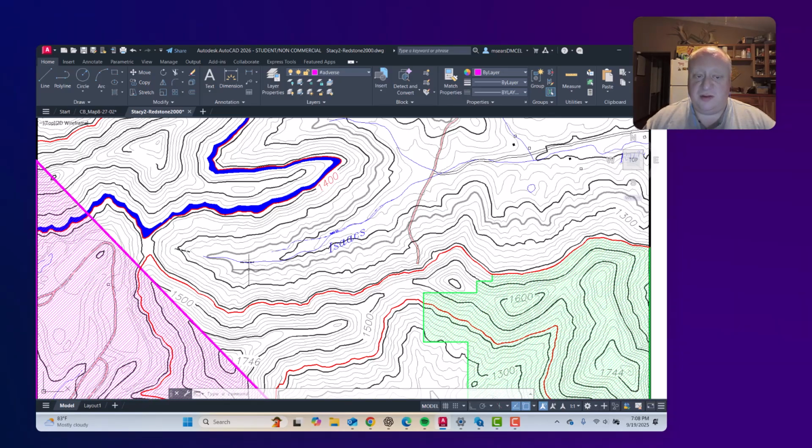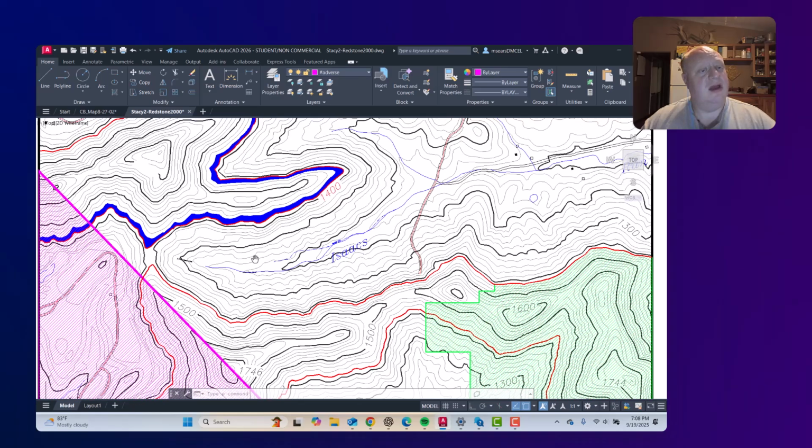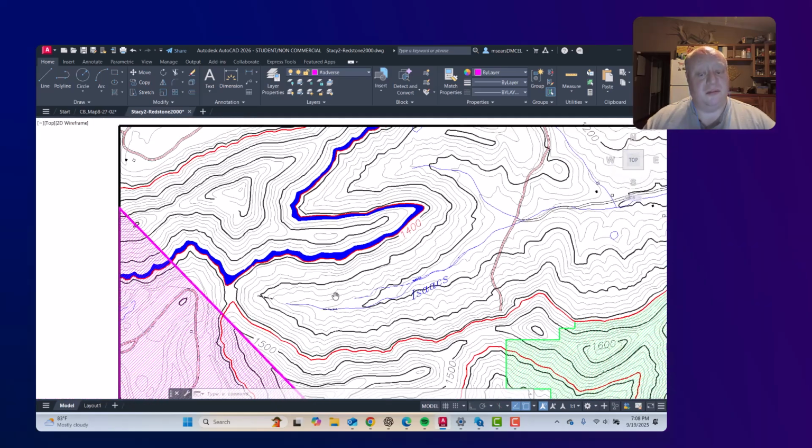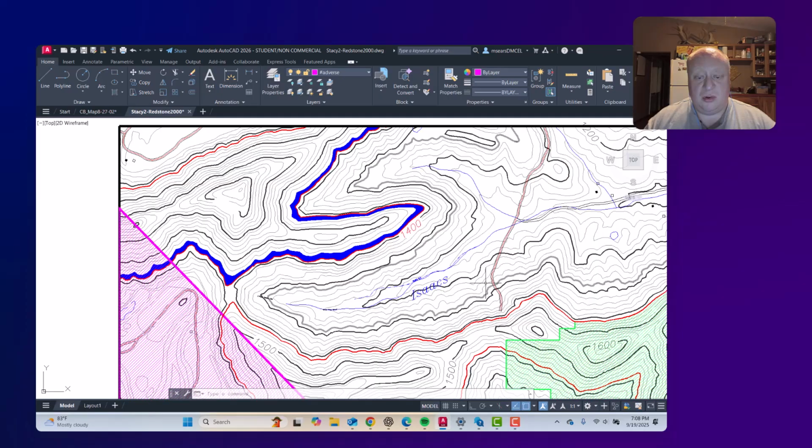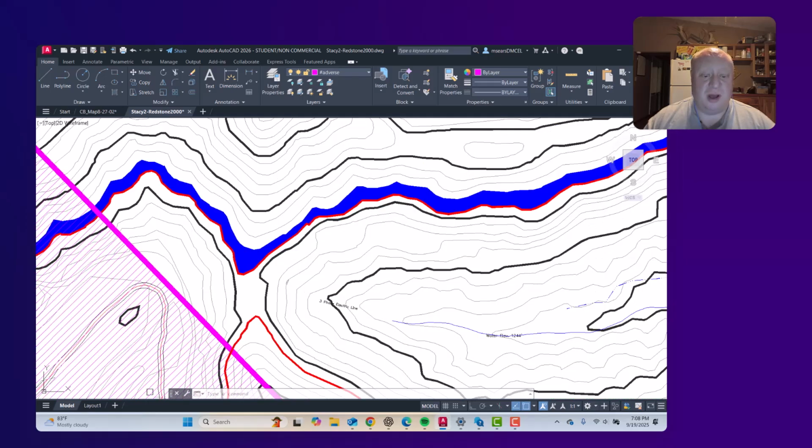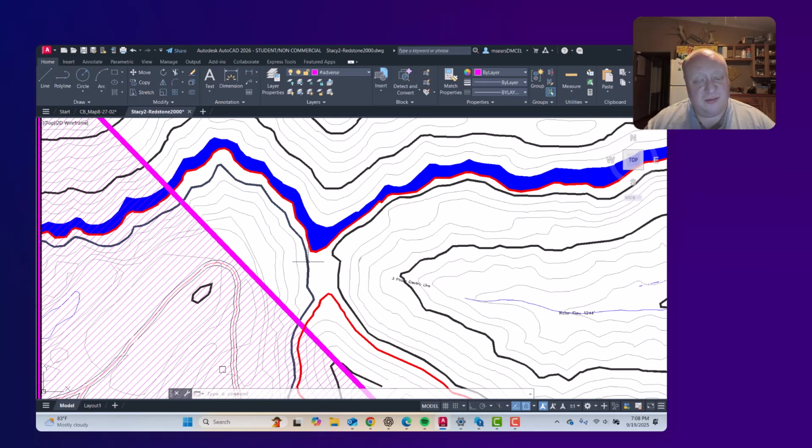With this particular property, you may decide you want to start somewhere else. For example, do you want to start over in here, maybe? You could build a new road and come over this way. It's near the property line, but there's some space here. You only have to be 300 feet or more away from a dwelling, unless you have a waiver.